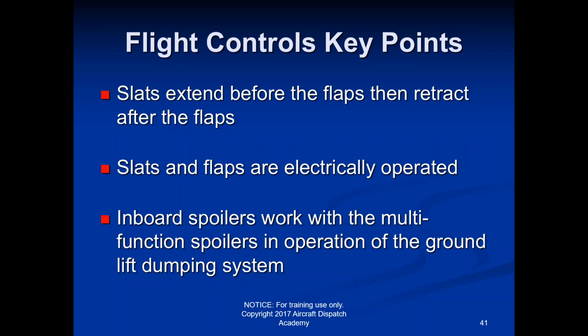When you consider everything that it takes to stop an aircraft, there's a lot of interesting things. In a lot of cases, aircraft can totally stop and slow down without using the brakes at all, depending on the length of the runway. But ultimately, the idea is to get the aircraft to stop itself without having to use too much brake. The brakes will heat up really hot, and like I said, the wheels are already really hot from being on the ground, spinning and carrying the weight of the plane.